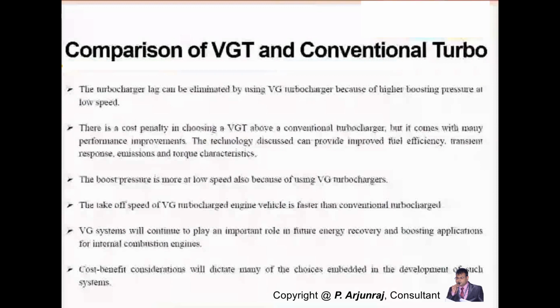But again, there are some equipments where some of the OEMs try to put the NVH aspect into it, where they also find out what is the decibel sound coming out of the turbo, which is basically in the form of a whining noise. So people are doing that. That is one problem that we have to identify. The noise is not only because of one source. Yes, of course, I agree. Flywheel also contributes, and not only the turbo, even the chain or other systems. There are a lot of things that will also have noise.